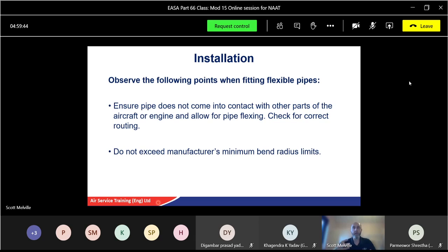So again, the pipe should be ready to fit, as in the design fit. You have to make a pipe up? Well, that's not normally the case. They must be airworthy checked. You can't just go and make your own pipe up. But again, there could be a modification. The new pipes come out, but it's not quite right. If you bend the pipes too much, well, it puts too much stress on it. So again, it must be right to do the job.